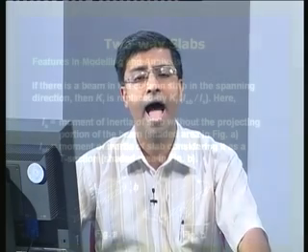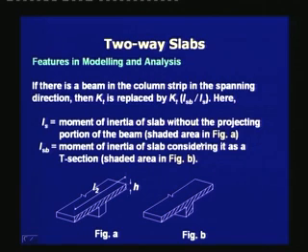Thus, if there are beams in between the column lines, which may be present in a two-way slab with deflecting beams, in that case we reduce Kt to consider the flexibility of the beam also, and it is changed proportionately.